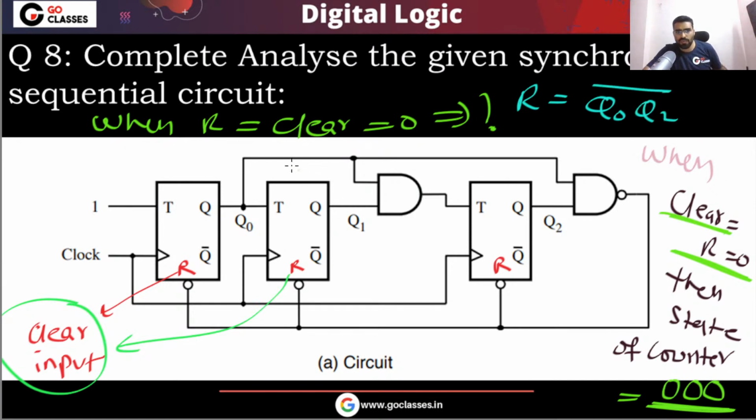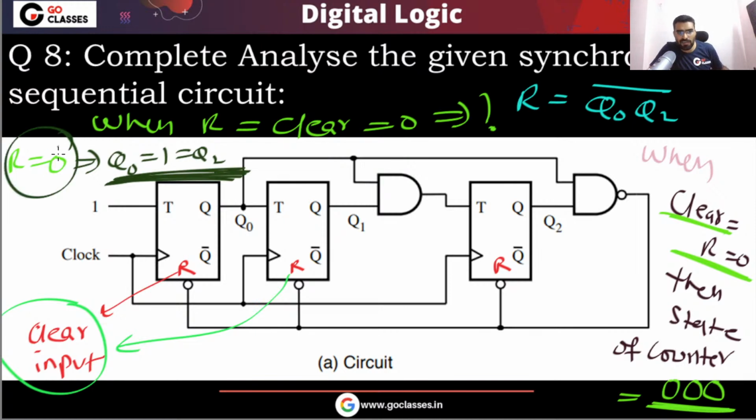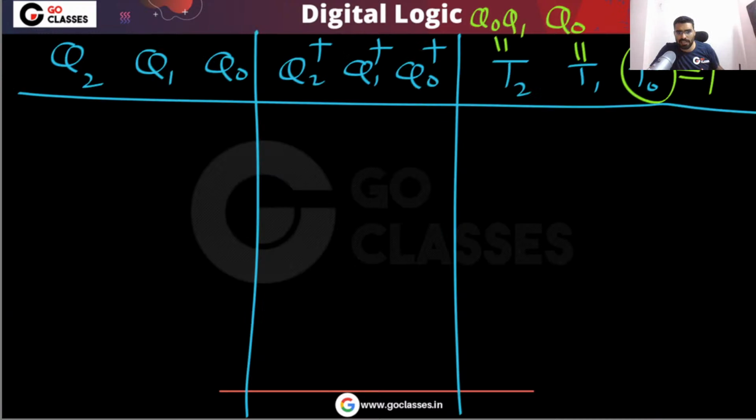So when this R will be 0, it simply means that Q0 is equal to 1 and Q2 is also equal to 1. So both are 1. When Q0 and Q2 are both 1, then what will the next state be? Then the next state will be 0, 0, 0. Okay, so this is the idea.